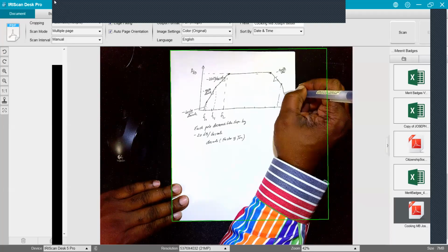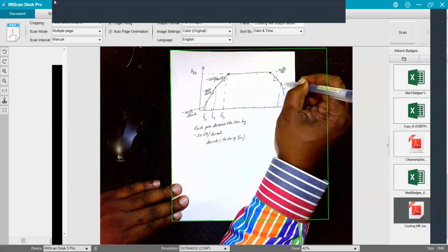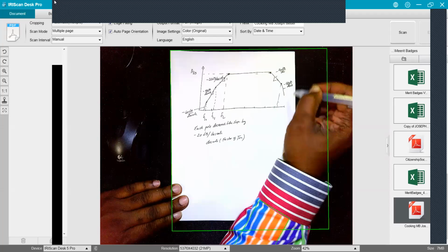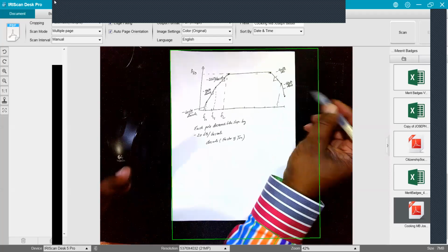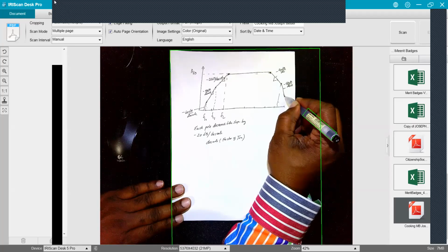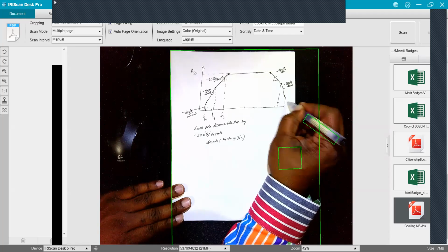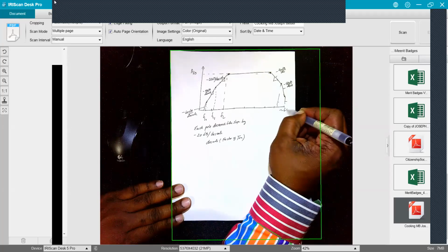And now this slope changes to a minus 40 dB per decade. And if we go higher and higher, this F sub beta roll off will make it roll off at minus 60 dB per decade.